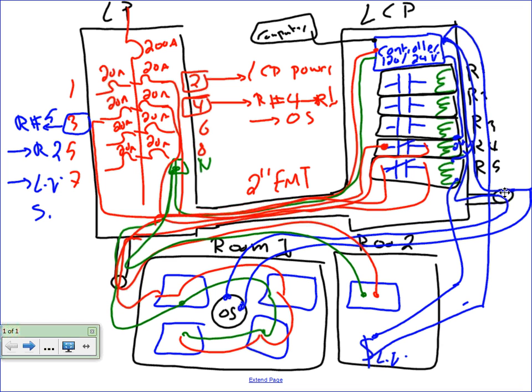The last thing I want to say is power pack. There's a term you're going to hear about: power pack. If you don't have cash on you and you don't want to buy this control system, right? You don't want to buy a whole lighting control system, and you really want an occupancy sensor in this room. No lighting control panel, just an occupancy sensor in this room. You know what they do? They have a power pack.